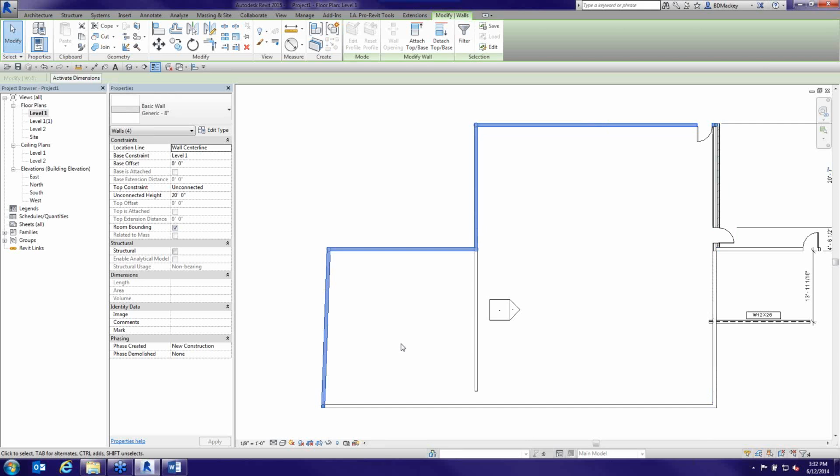So that's one of my tips too for the tab key is, man, hitting that tab, going through a chain of walls, but not only just a chain, a length or a given object of wall. So again, you pick one, hover over on something else that's joined, tab, and it'll grab between the tab. So I always like to show that one too.